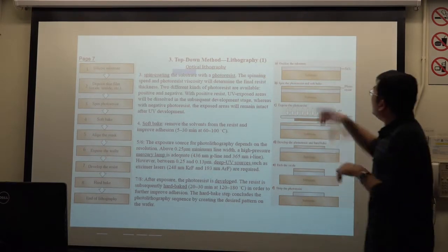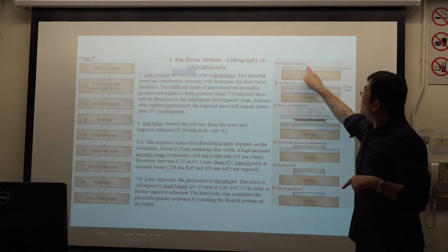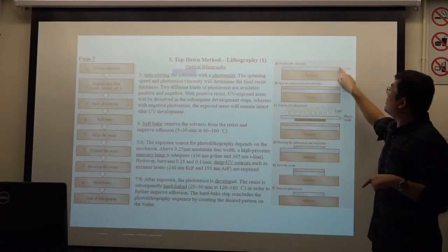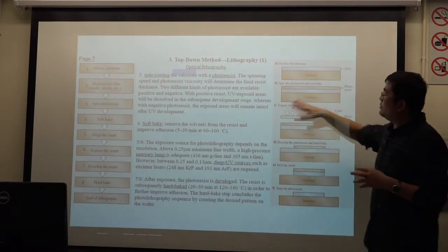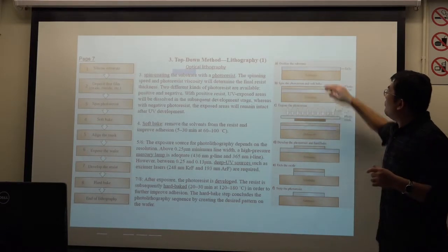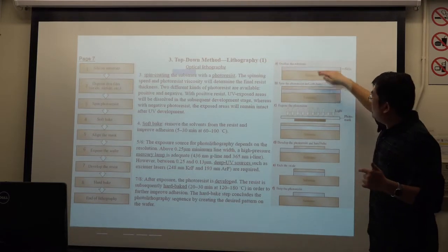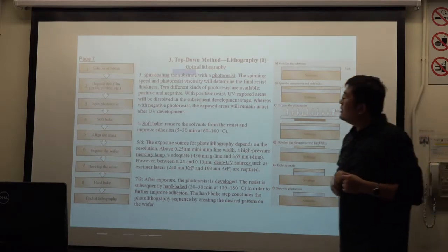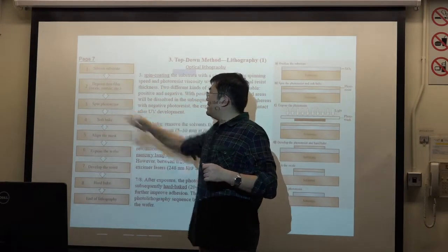You can see here, this substrate. Then we can deposit on or oxidize the substrate, oxidizing the silicon from the outside. This first step does not relate to the physics; it's very standard. Maybe we can also deposit other material above the substrate. Here, we just oxidize the silicon outside. The third step is to spin photoresist.